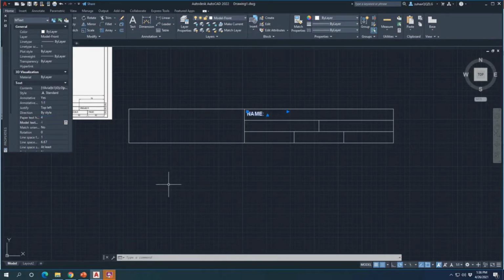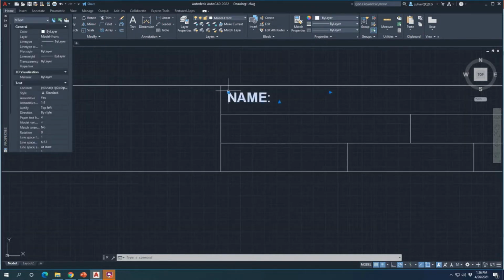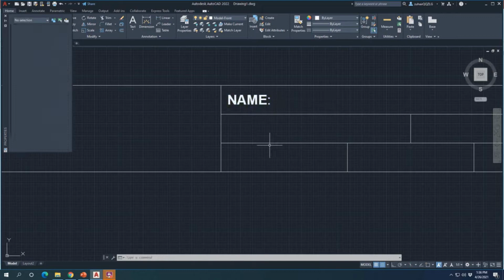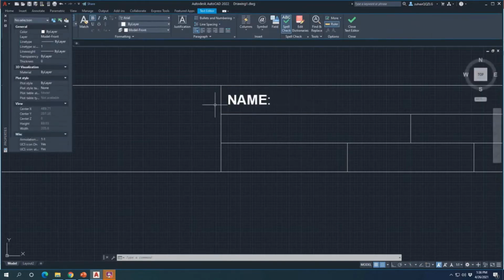Okay, so now the font had been changed to 4 mm, but it's still not really in the middle, so just going to move it a little bit more. And sometimes it's really hard because we have the polar tracking. You sometimes have to click off all of this in order for you to move it freely. Okay, something like this, or maybe move it a bit.